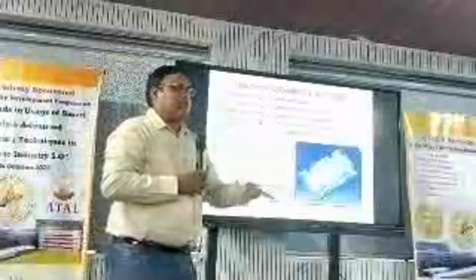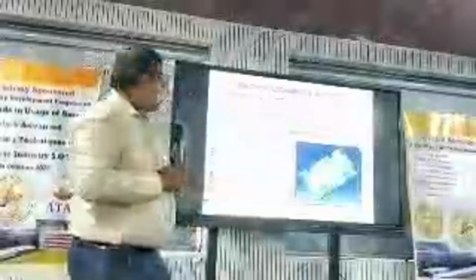So, using some of these techniques, we have designed the raft and compared the transmissibility curve of the raft. These are the pockets for keeping the isolators. It has to be designed such that its center of gravity is low, because if the CG is at some height, because of the rotation it may topple. There is a chance of toppling, so we have to make the system such that the CG is as low as possible.